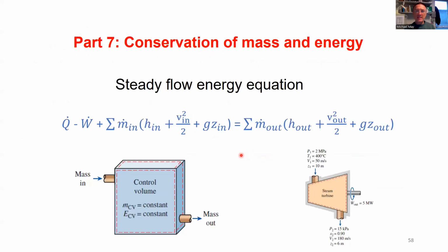Those last two examples are, strictly speaking, open systems. We can still apply the first law to them because we're only being asked to work it out in terms of internal energy. But generally for open systems, we would apply the steady flow energy equation. So we'd be taking into consideration enthalpy rather than internal energy, and the velocity and any potential energy aspect as well. In this section, we've applied the first law to closed systems.